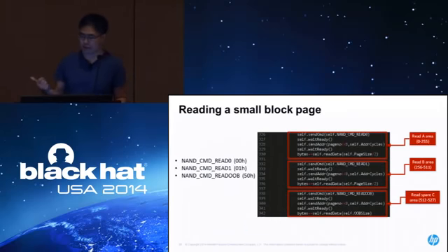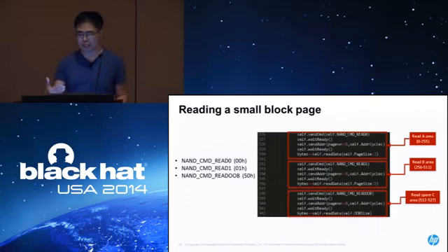So from here, it's sending the command from the first line, and it's waiting for the ready signal. The second line is 327, and after that, it's sending the address, and it's waiting for the ready signal, and then it's reading data. If you go to this function, it's reading each byte, each page. But the good thing is that the FTDI chip itself will take care of all those underlying I/O and strobe operations. So you don't need to take care of that.